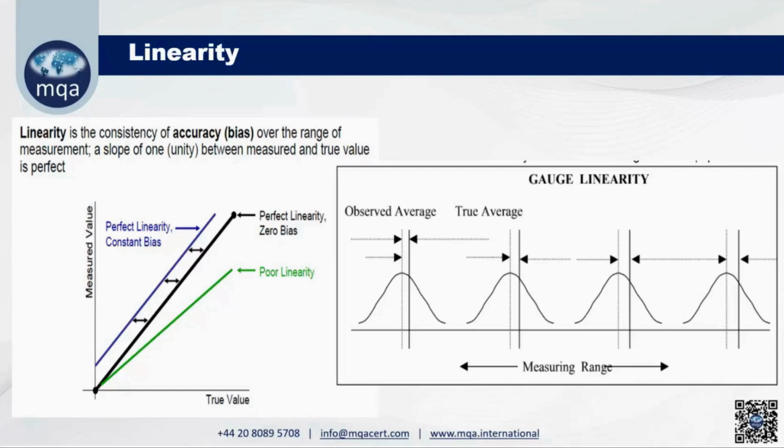The service people do lapping on the vernier jaws. The jaws are okay, but there is an error induced because we are removing material from the jaws. So our zero error will not be there. It will not show zero error. When we close the jaws of the vernier, what will happen?